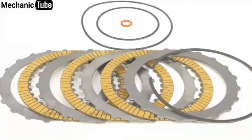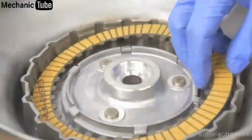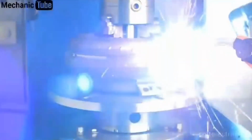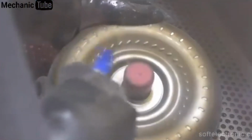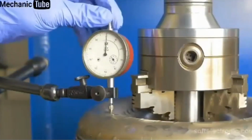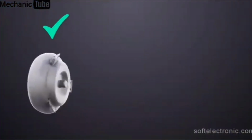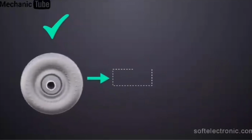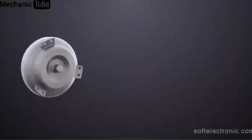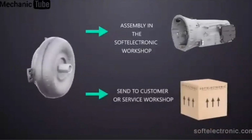The Soft Electronics team only supplies original parts from world-renowned manufacturers. After the necessary components have been replaced, the torque converter is assembled and the two parts of the housing are welded. This is followed by cleaning of the housing with a sandblasting machine. Finally, a measurement of the deviation from the axis of rotation and balance is made, and depending on the model, clearance and tension are checked. If all the measurements match the reference values, the torque converter is marked and the results are recorded in the Soft Electronics database. The rebuilt torque converter can be reassembled to the automatic gearbox or sent to the customer with the corresponding warranty card.